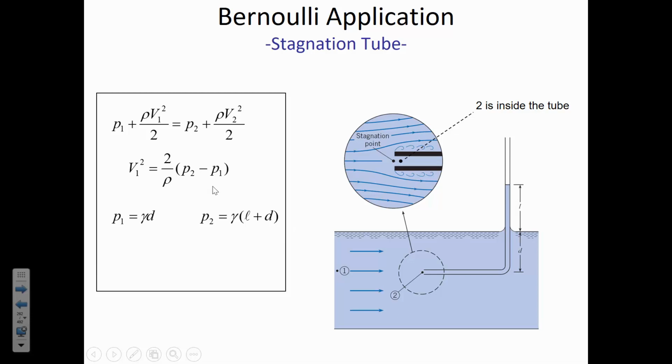So this is just another way for us to understand what's the pressure at 2, and the reason why they're different is, remember, some of the velocity that was at 1, that energy that was wrapped up as velocity, has to go somewhere when this streamline intercepts the stagnation point. And so that extra energy is immediately transferred into additional pressure.